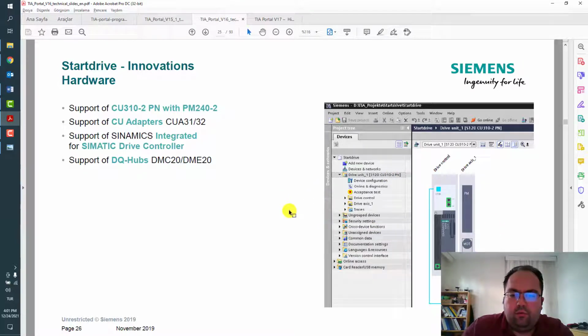Also, it's important to know that when you are working with new hardware and new software, it's always a good decision. It depends on the customer side also. For the maintenance guys, it takes time to go to the next step, get the licensed CMS software and install it on their own PCs. So that's why sometimes you keep using the old version of TIA, because after the commissioning it's not possible for maintenance guys to open and diagnose.